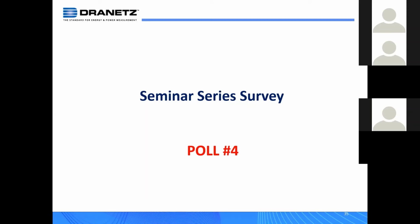Okay, so why do you specify 16 hertz and 25 hertz test frequency on an HDPQ? This is from Johan. Johan, can you chat up? I don't really understand your question here. Our HDPQ family can measure at 16 and 25 hertz, so we do tests for that. Those are railroad frequencies, as Ken mentioned. We've had a number of applications with transportation companies in which HDPQ was used to monitor. We see here 25 hertz, 20 hertz, the rail frequencies. So it was used in those types of applications.